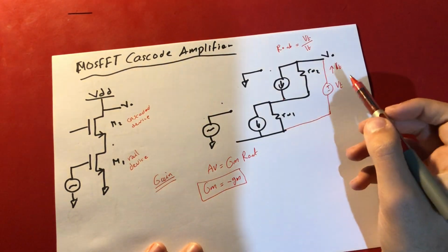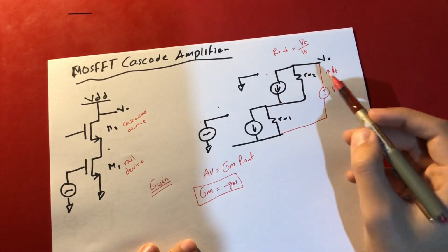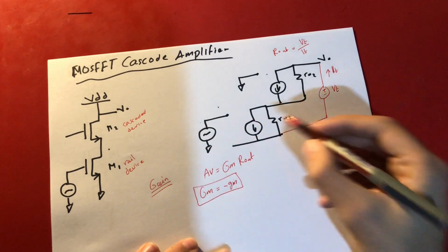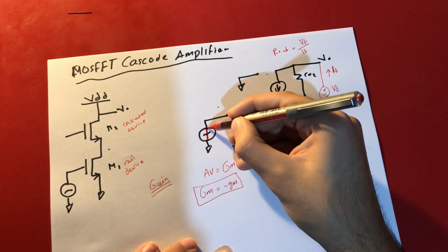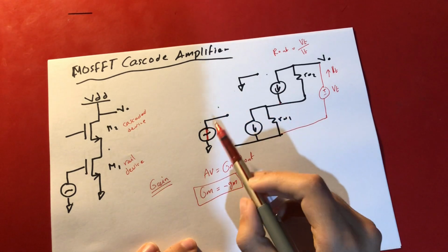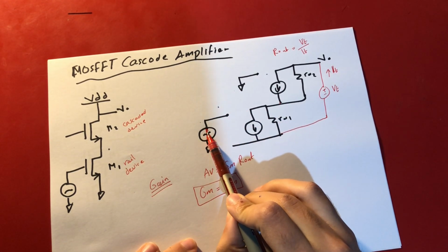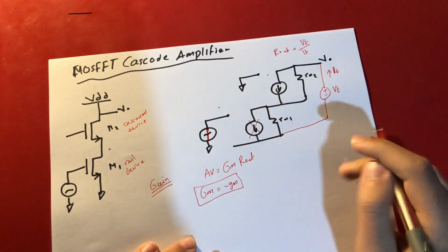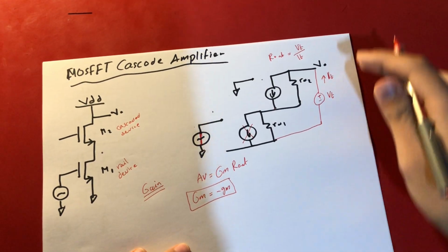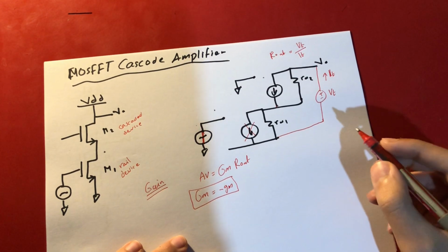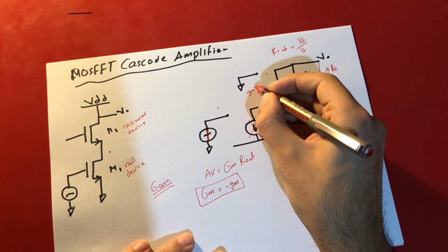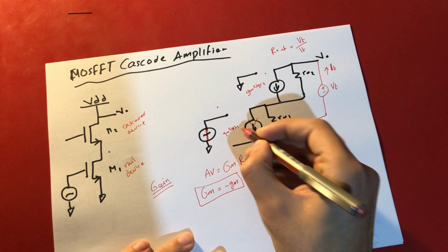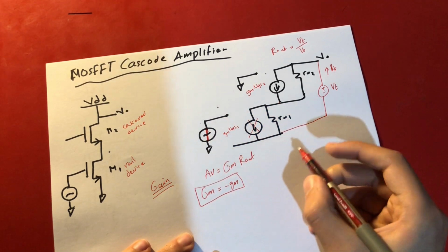Also, when we use this analysis, we short circuit or turn off or kill any other source. So this source here becomes 0. Now, because this signal is 0, and this one depends on this one, right? So this also is not in the circuit anymore. This is gm VGS2, right? And this is gm VGS1. So this is 0 and this is 0.